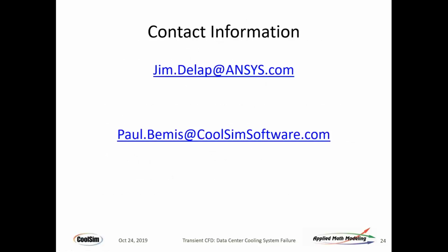I did want to leave enough time for questions, and we are running on time here. So the first question I think I answered: is it possible to do a transient CFD analysis in a site that uses both DX and fluid at the same time? The answer is yes. The DXs are fairly easy. They're on-off. So if you lose a DX unit, the liquid-based system has to absorb all of that extra heat, and you're going to see some temperature gradients in that room as a result of that failure. So the answer is yes.